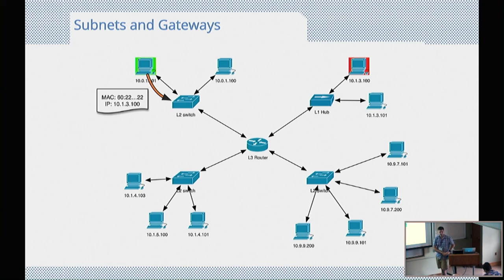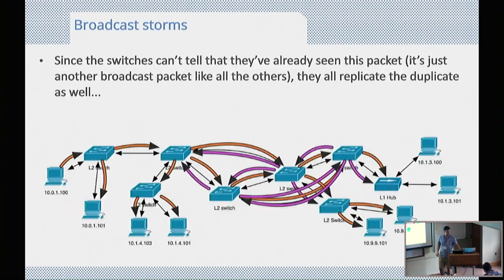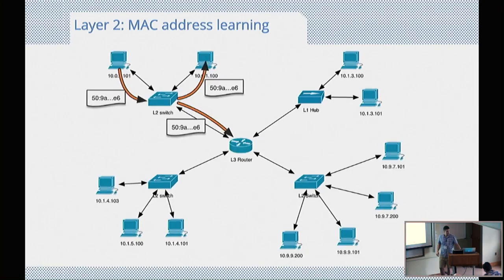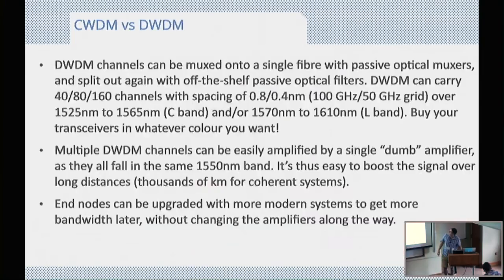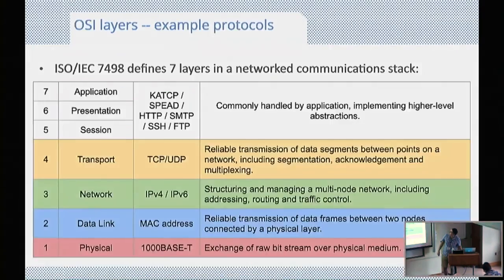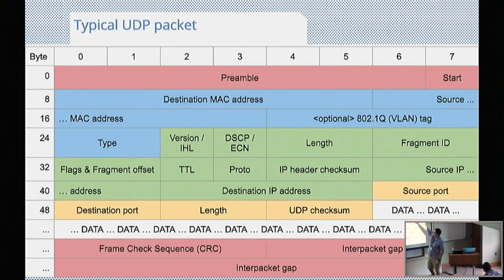Are the clocks accurate enough that you don't have to worry about differences in clock rates? That could affect how much loss you have in these faster systems. So Ethernet used this preamble to sort of lock on, because they're all asynchronous. If you remember one of these slides here somewhere, there we go. The first bits that are on the wire are this preamble, and that allows the receiver to sort of lock its clock and find the bit edges. Yeah. That's the intention behind that.